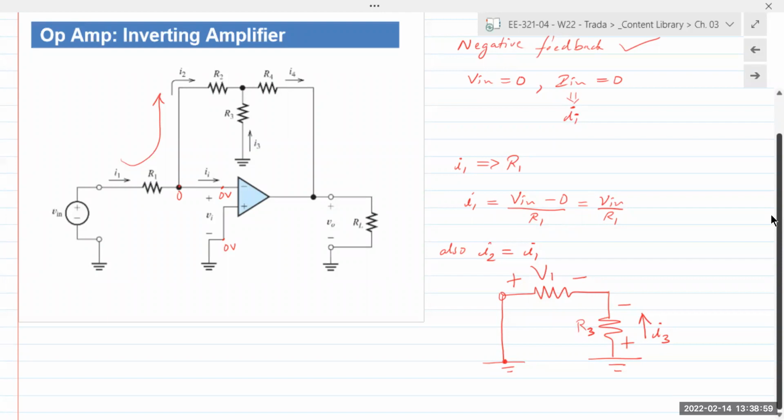Yes, the voltage across here is plus here, minus here, because you can consider that to be in parallel with R3. The current always goes from plus to minus. For purposes of analysis, think back to the first chapter of 201. It does not matter what assumptions you make regarding the voltage polarity or current directions. It absolutely does not matter. You can take the opposite of logic, opposite of all physical laws, but as long as you're consistent within the problem, your answer will always turn out to be correct.